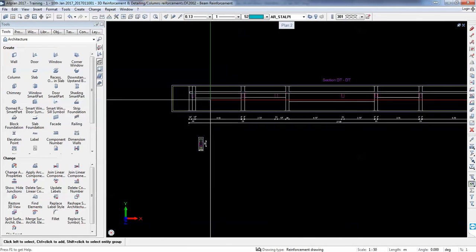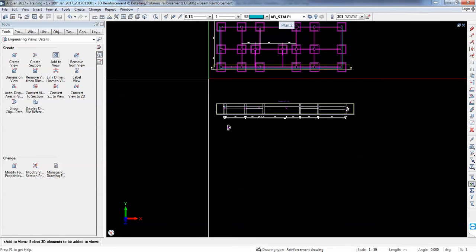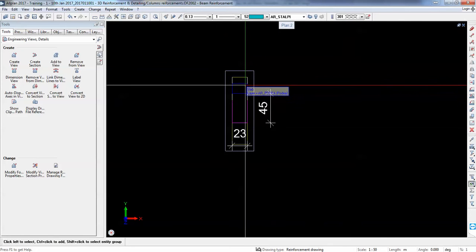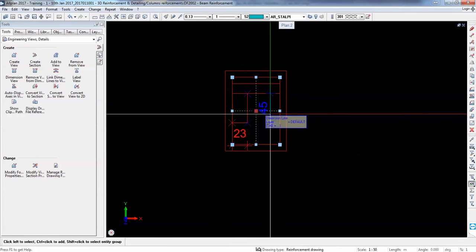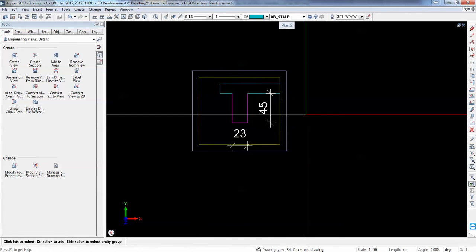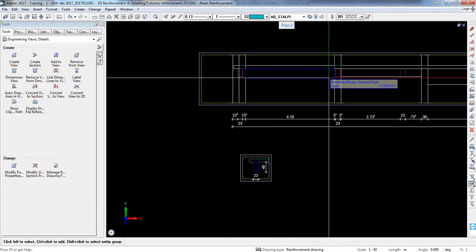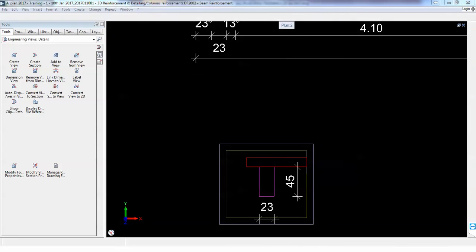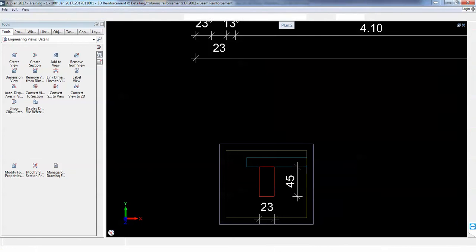Okay, now going further, if I have to add the slab also to the cross section I just created, I can do this. So now I also have some slab, so in this situation I'll do the same trick of extending the view. So it was shorter, now I can see the beam with the slab. How can you merge the slab with the beam? The only trick I did was this. I placed the style area, reinforced concrete. For this one, it's the same.